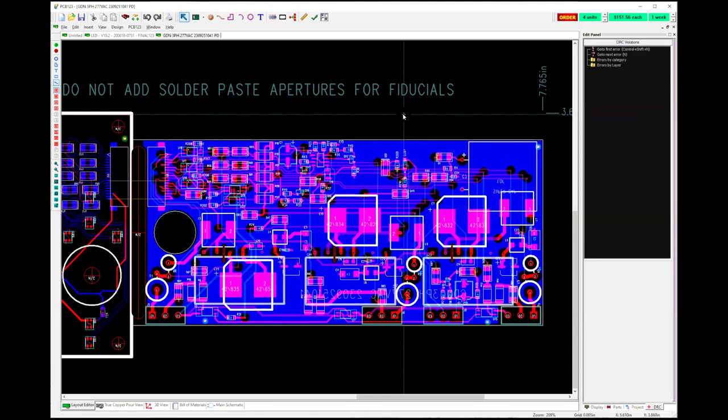And you certainly wouldn't want to auto route. Matter of fact, I wouldn't want to auto route pretty much anything using the auto route tool. Sometimes I'll use it as a reality check. Do I have enough room on the circuit board to actually do the design? And if it can auto route to 80%, just hitting the go button, then I pretty much know that I've got room to do it. Otherwise, I go in and wiggle things around, get a little more room.